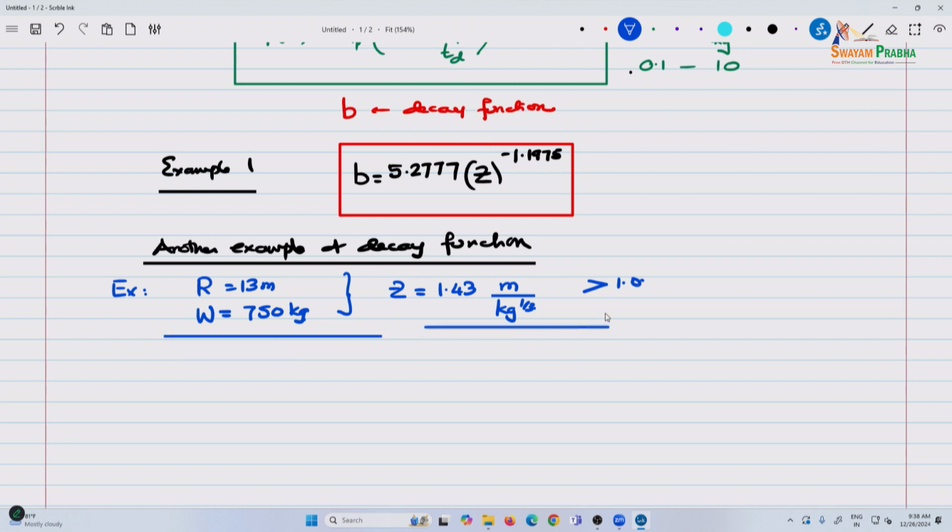For these parameters, you get P_so is equal to 415.5 kilopascals. Then the impulse I_s is 1144 kilopascal millisecond, and t_0, the positive load duration, is 15.3 milliseconds.